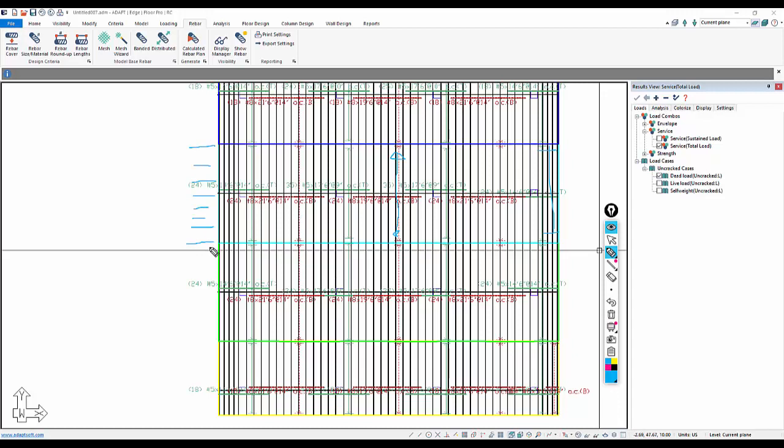Something like that. Okay, so if we take the 336 divided by 7, that actually results in a spacing. If we had number 8 bars, the spacing would be 48 inches on center. So at this section, the required reinforcement is controlled by minimum requirements, which is 6 square inches. That technically is 8 bars. However, there's another thing that's happening.